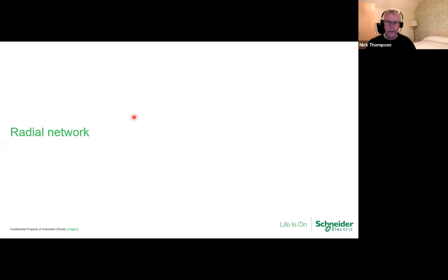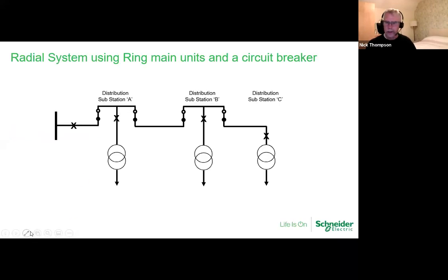However, moving on. So let's have a first look at a radial network. So a radial network typically is going from the supply circuit breaker, which is this one here, through to an endpoint. And quite often you would find a radial network with just a piece of cable, depending on however long it's going to be, going from the circuit breaker to a circuit breaker, and then maybe a transformer or a switchboard, depends on the site.